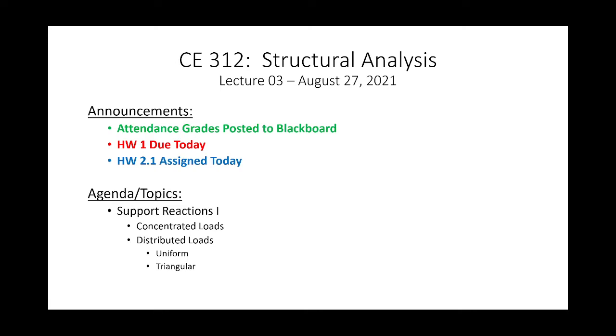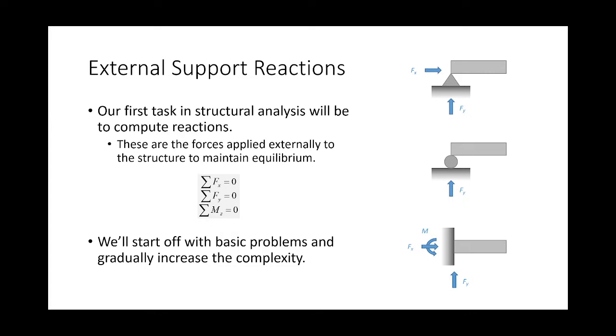Now, this is arguably the first task in any structural analysis course, and I'd argue it's one of the most important, because everything that you do in a structural analysis setting in terms of identifying response for the purposes of design, ensuring that your structure meets serviceability limits, et cetera, tends to always start with this. The idea is that you're trying to determine the external support reactions that keep your structure in equilibrium. And from those, you can then determine shear and moment diagrams, axial forces in trusses. You can determine how much the structure is going to deform.